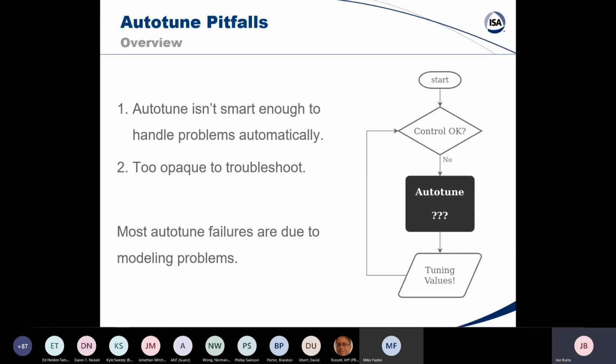If you had a perfect model of your plant and you knew it wasn't ever going to change, then open loop control would be just fine. If you always knew what pump speed to be at, you always knew where your disturbance would be, and you always knew what your pressures were going to be. But in reality, that's never the case. You want to use feedback control to correct any changes, any changing situation in your plant. And so that's why it's so commonly used.